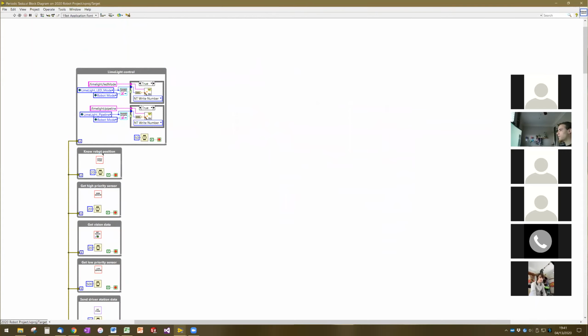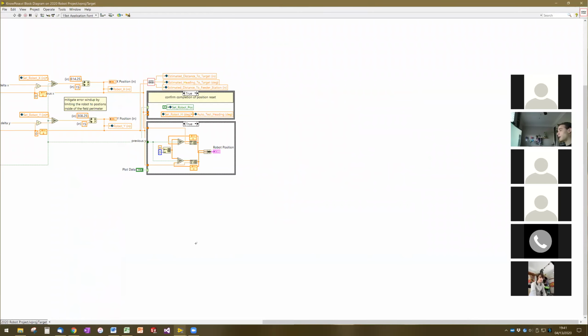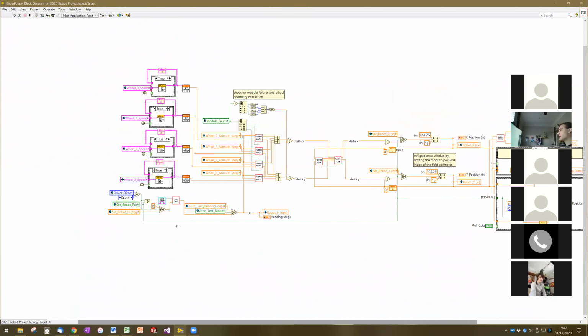The other block that's running in parallel here is also sensor related. This one is pose calculation. So this is all of the math and all of the sensor readings required in order to estimate the robot's location on the field. Because those sensors need to be synchronized with each other, they're being handled in the same block. There are some nuances with the fact that this is not synchronized with the Limelight, so there are some challenges there, which could cause issues in edge cases. I don't know that we've seen that problem occur, but it is possible.